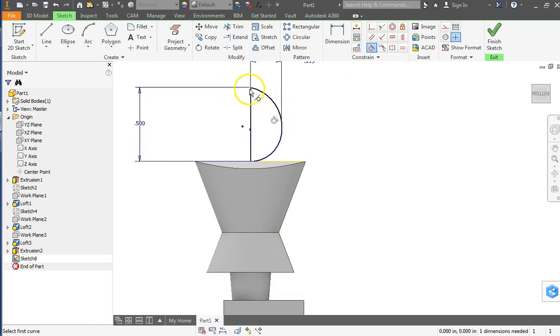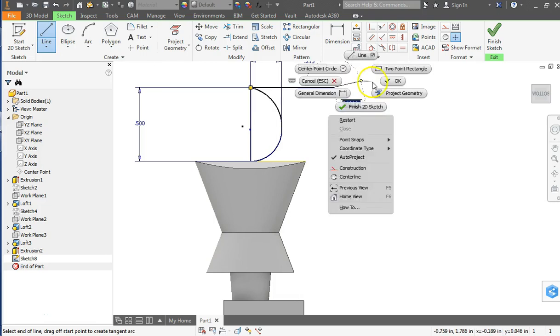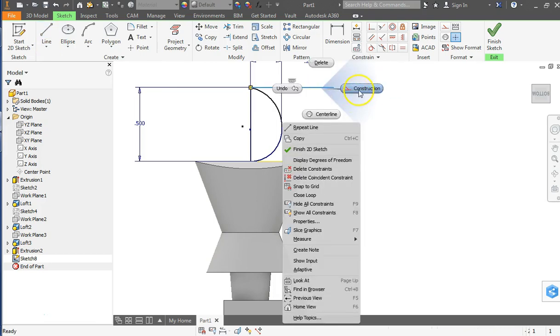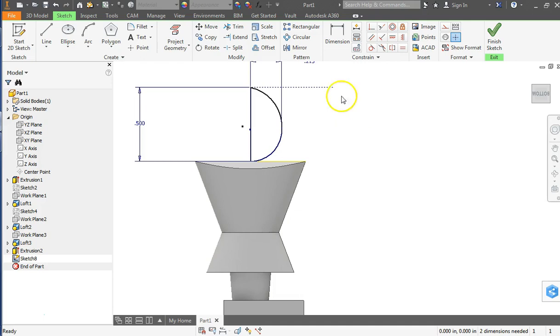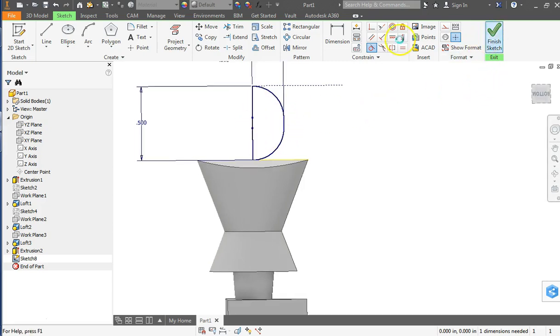And now I want to really go from here to a horizontal line that I can't reference. So I'm going to extend and create a horizontal line for myself. And I can even right click and call it a construction line, so it's dashed. I left click to unselect it, and then I can use the tangent tool between this and the arc. I want to make sure that that's smooth, perfectly level, so that when I revolve this, I don't get a point or a dimple there. Okay, and that's about the right size, so that'll be good enough.